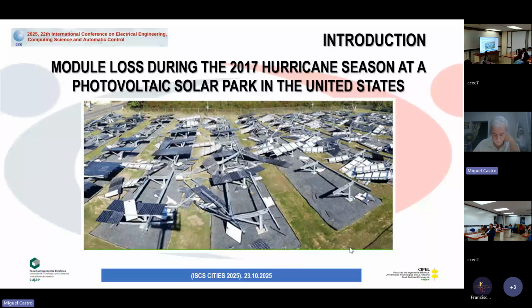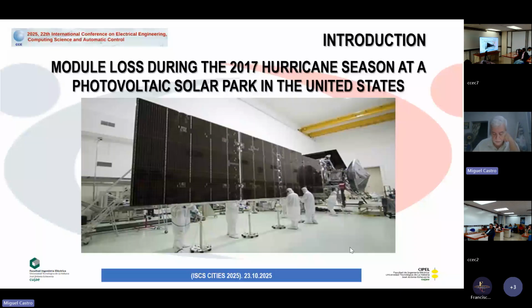The wind load test can be used to assess whether components within the module, including solar cells, interconnecting tapes, and electrical links, are susceptible to breakage, or whether fixed parts, for example brackets, clamps, screws, are likely to fail due to the uneven mechanical stresses occurring during severe wind loading. An example of how tests are carried out on photovoltaic panels is presented in the slide.